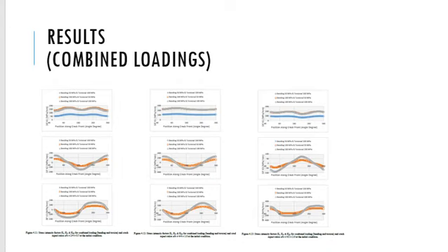The combination of large bending and large torsional load results in a large absolute K2. K2 has greater value at positions under 80 degrees. The largest absolute K3 values are found at 90 degrees and 270 degrees of the crack. This is shown for any crack configuration. The greatest value of K3 is found at the combination of large bending and large torsional loading.